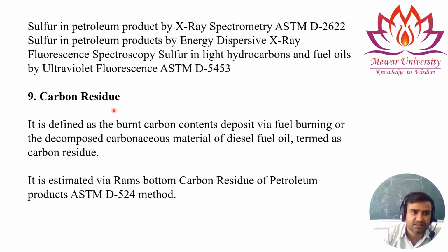If you read the definition, it is defined as the burned carbon content deposits via fuel burning or decomposed carbonaceous material of diesel fuel oil, and that is termed carbon residue. It can be estimated via Ramsbottom carbon residue of petroleum product, and the method is ASTM D524. Using this method, you can find out how much carbon residue is deposited after burning the fuel.